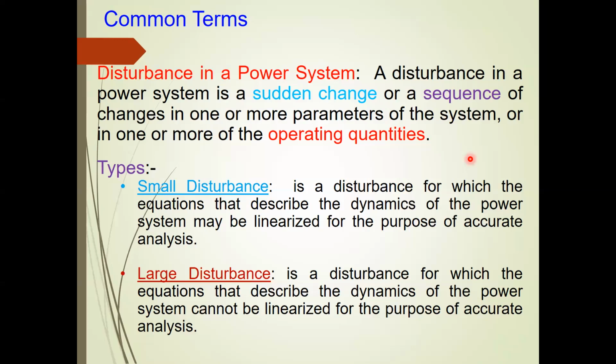But if you have a situation in the system where the demand is more and the generators which you have connected in the network are not capable of meeting the demand, then what will you do? Am I right? There the system instability problem will be much more severe, because you don't have any control on the load.